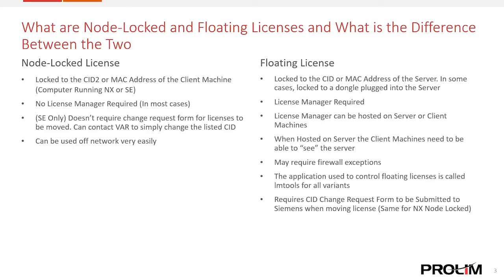Now, the floating license does have a tie-in to a machine, but on this side it's tied to the server. So for NX and Solid Edge 2020 and newer, it's tied to the CID. And for Solid Edge 2019 and older, it can be tied to the MAC address or a dongle. Dongle being a little USB drive that plugs into the server that verifies the license.